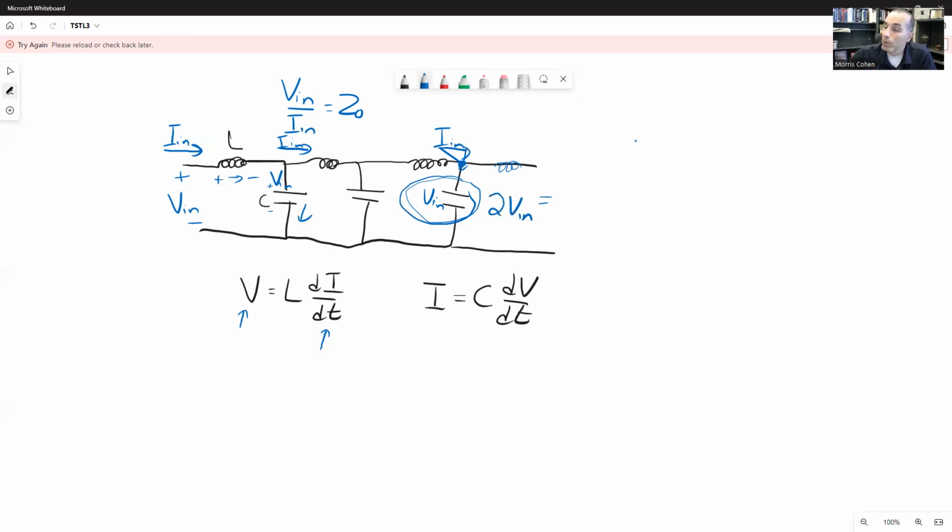Right? We're going to double the voltage compared to what we thought would be the case, compared to the value of the voltage that comes in. Right? We had 1 volt, 1 volt, 1 volt, 1 volt, 1 volt, and all of a sudden, we just kept pouring that current into that capacitor and continued to charge it up because nothing could continue down that transmission line. And so we got 2 volts instead across this last capacitor.